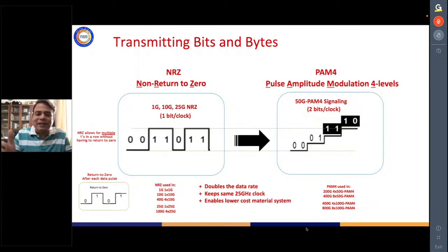Depending on what kind of signaling you are doing, if you're doing non-return to zero, a zero corresponds to 0 volts and one corresponds to a high voltage. Or you can divide the levels of the analog signal into multiple levels and represent every level by a particular bit pattern. So you do amplitude modulation, right? So you do different kinds of signaling,